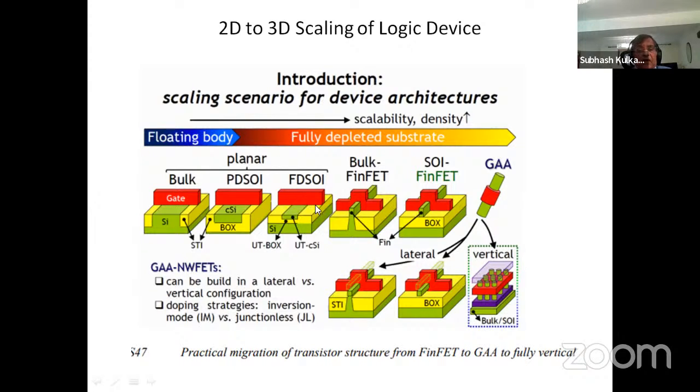transmission. Now, from these planar devices, we are moving to using FinFET. FinFET is basically, we got a fin of silicon sticking up and we put a gate around it. So the cross-sectional area between gate and the fin is increased more than the cross-sectional area we had before. So the amount of current that you can pump through this is much higher than what we were able to do with planar devices. So you get much higher currents. That means you can get more power coming out of these devices. This can be built on bulk as well as on SOI wafer. So that's the phase we are in.